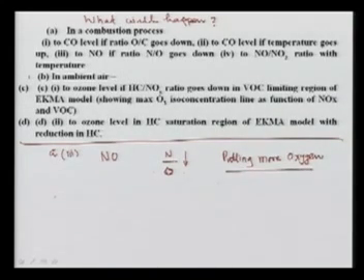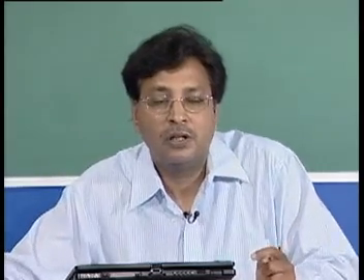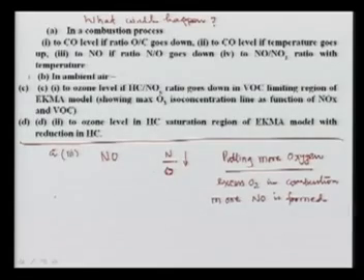And we all know if there is excess oxygen in combustion, more NO is formed. And recall that what was that NO used to be? We used to call it thermal NO, or the thermal NOx. So, the answer is, if this ratio is going down, NO is going up. Under this condition, NO will rise.